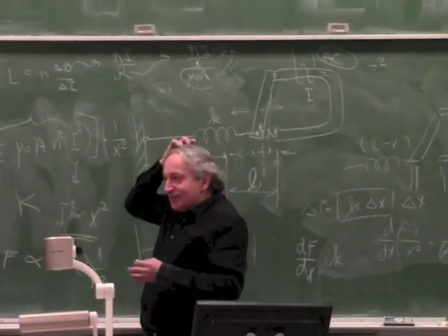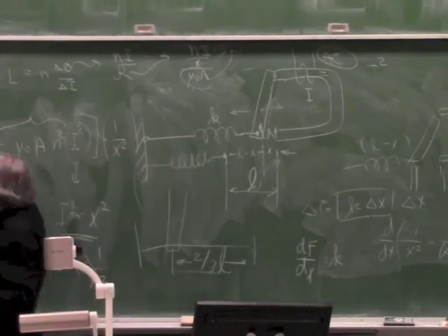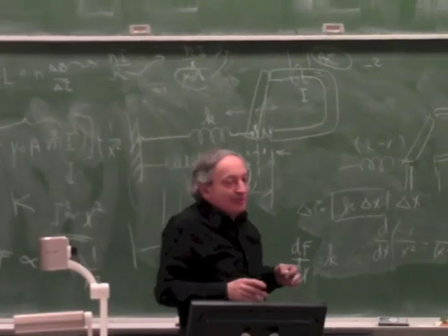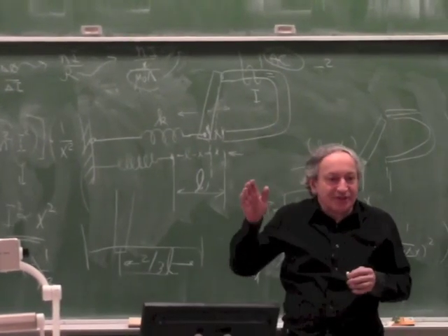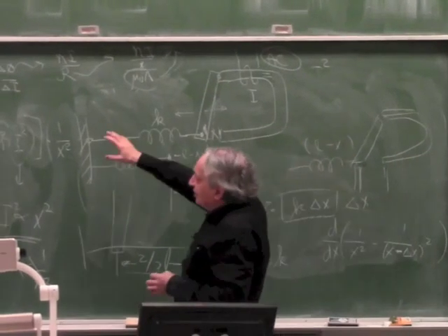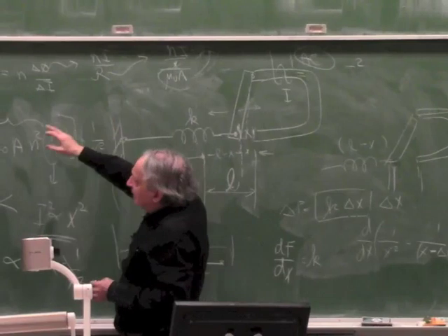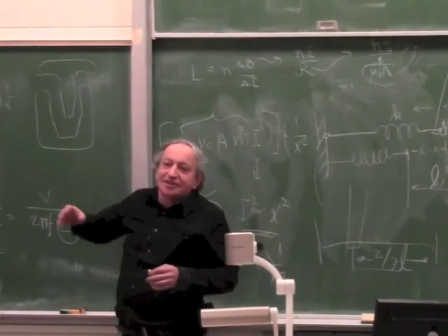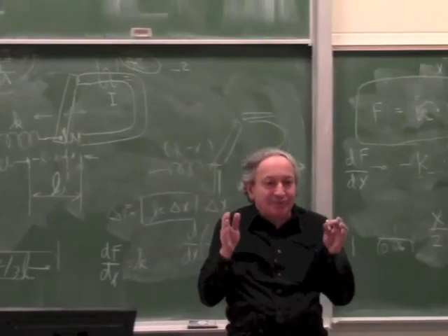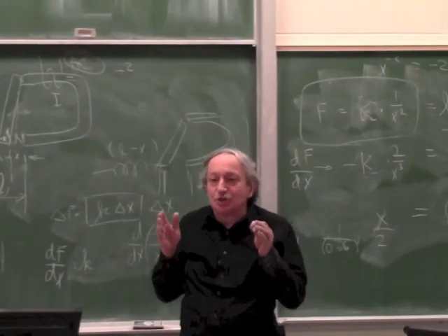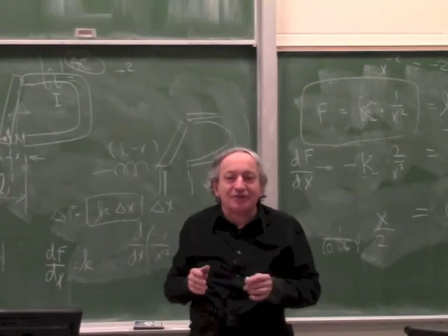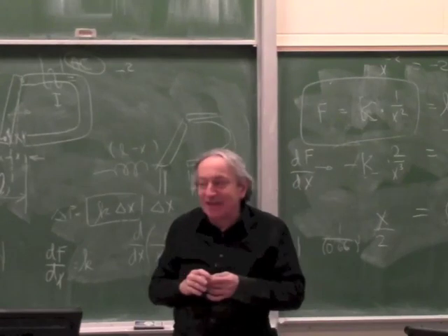Now the reason this doesn't happen is this whole model relies on linearity, and we learned before when you have magnetic materials they saturate. So this model that says that we can cancel out the nonlinear behavior by running it from AC, this only works if everything was linear. In other words, it works if we had a very big air gap. If very big air gap, there will be no saturation. Okay, but then we are wasting a lot of the travel of the actuator and a lot of the potential force if there's a big air gap.